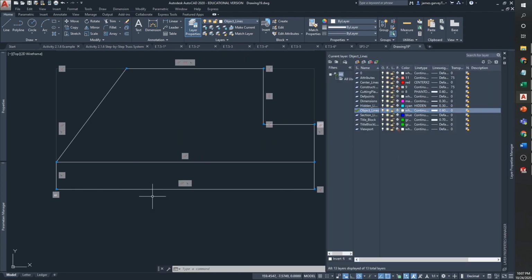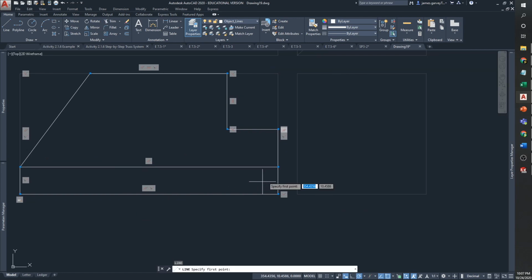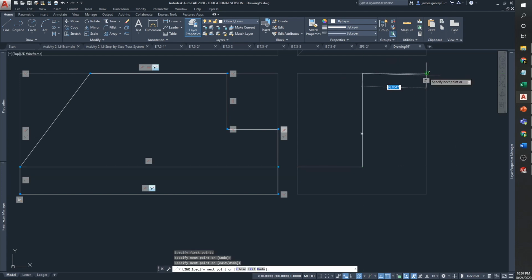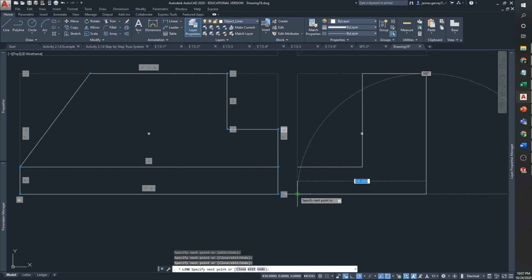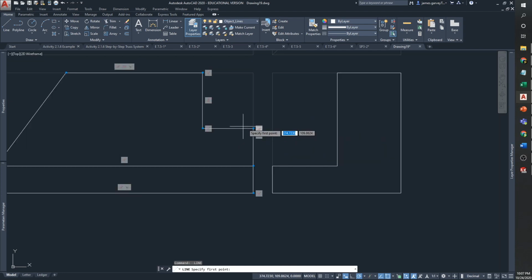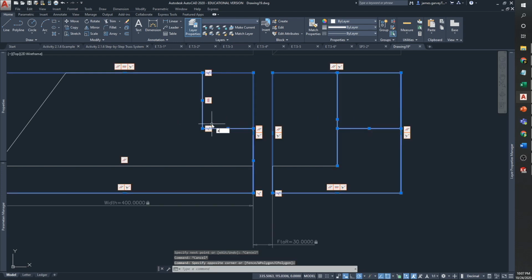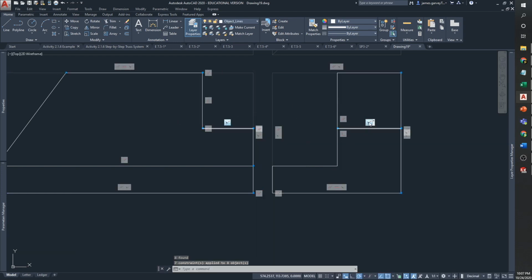My right view is going to be here, all the way up, all the way over, all the way down. And I'm going to track from here. So in this case, I do want to be not super sloppy because I want to make sure that when I do my auto constraint, it's going to make a collinear constraint between these two lines. So select those two, auto, and that did add that collinear. So those should move together after I'm done with everything.